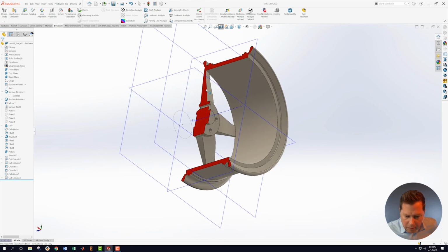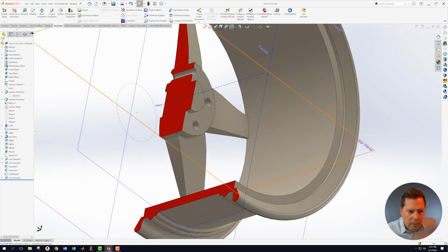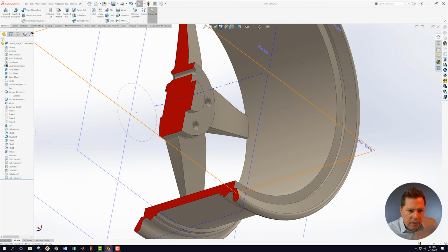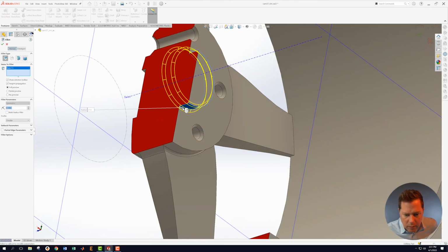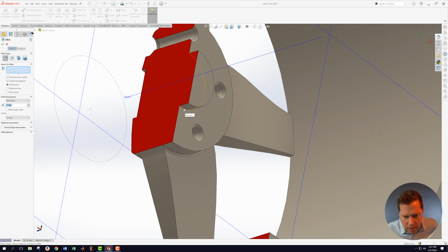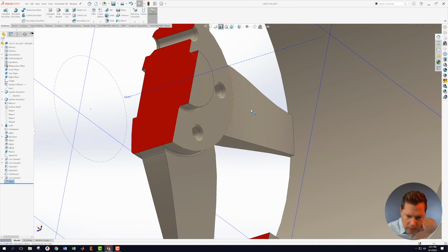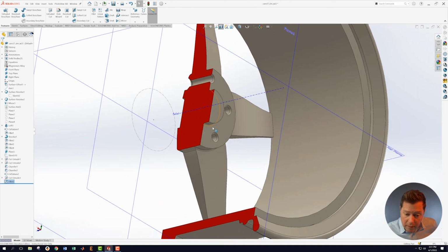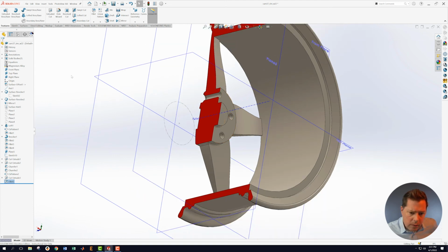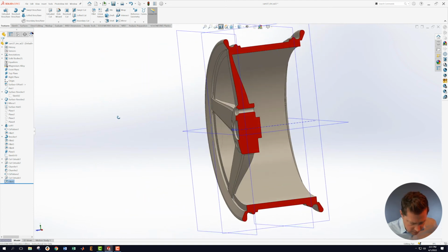That's okay. Better for me to go add in that feature because it should be there. Even if it causes my mass to be off a little bit more, I prefer that I get the thing the way we want it to be. So it's not what I wanted. Clear that. And that's a 0.1. That makes sense that we would have a fillet down there from a mechanical point of view. We want to reduce stress riser in that area.